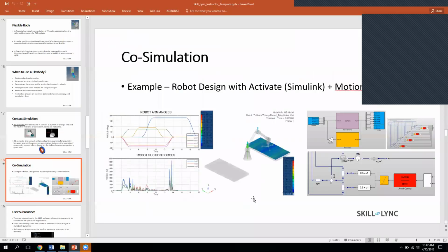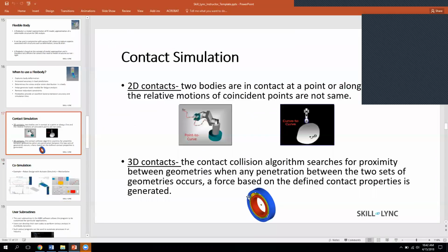That's because the ball bearing, even if it has a single point of contact, in the sense, it cannot have a single point of contact, because if you consider the ball as a 3D sphere, then you consider the outer race, the middle race and the inner race. It's called the outer race here, the blue part, the green part is the middle race, and the red part is the inner race. So the ball has contacts at all these 3 locations. So it cannot be just a point contact. It's like a sphere, and it's interacting with all these 3 regions. So then we have to define a 3D contact there and not just a point contact. That's what I'm trying to say. I am basically talking about the ball bearing for this particular simulation. Maybe there can be an example where it can have a single point of contact, but for this example, it will be a 3D contact. Okay, perfect, guys. I hope that makes sense.